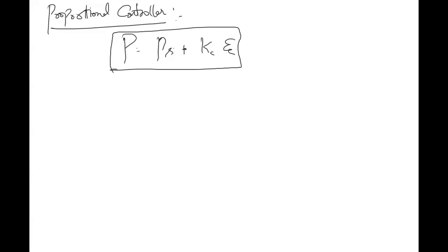Clear. So that is your steady state pressure. How do you generate the transfer function? What is the transfer function? Actual variable minus PS is equal to Kc into the error, minus the steady state error. When the system is at steady state, the error is 0. So capital P equals Kc into capital E.